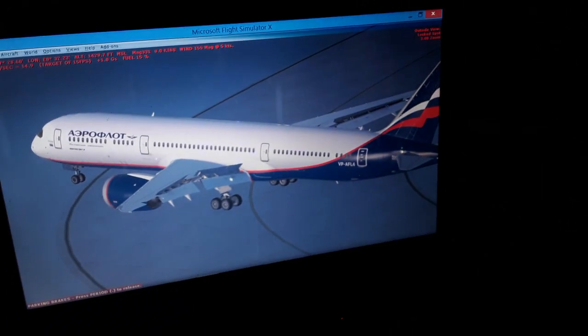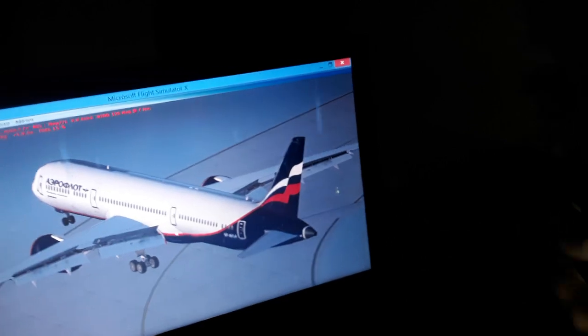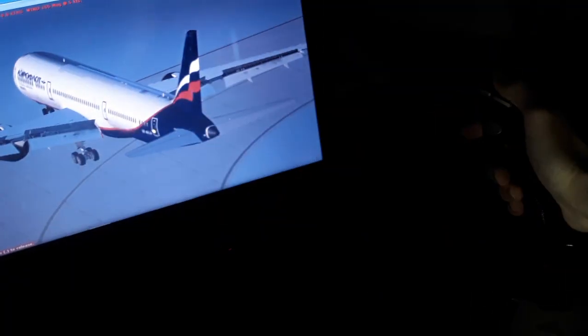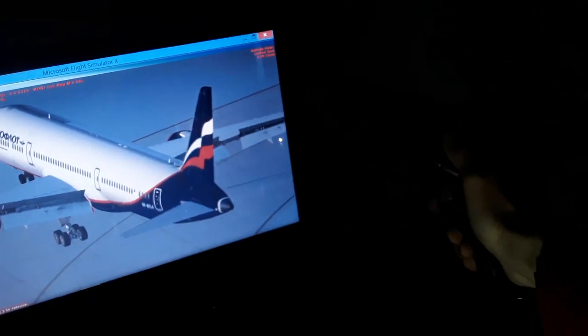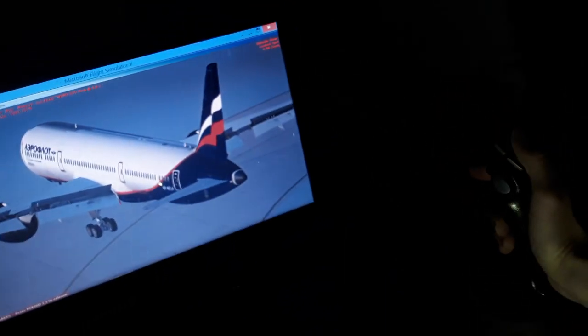So also over here, you can see we have this axis, the lateral axis from wingtip to wingtip. It's the pitch axis. In the Airbus we use the side stick back and forth to move the elevator, the horizontal tail of the aircraft, or horizontal stabilizer elevator, to climb and descend the aircraft, as you can see. So in the Airbus, back and forth, the elevator up and down, you pull up the weight or you pull down the weight of the aircraft.